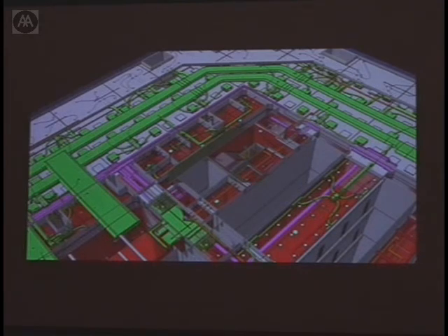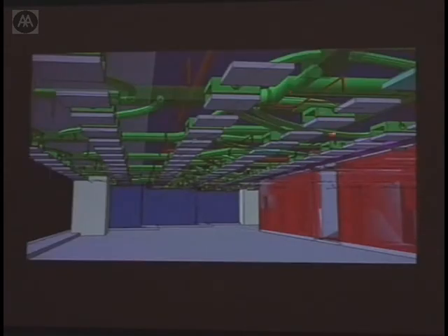And what we found is that the tools that we use allow us to capture pretty much every single miscoordination clash. What's interesting is that not only did we find there were a lot of clashes, but over half the clashes were within that one consultant, i.e. the mechanical guy clashing with himself, right? So his HVAC department would clash with his plumbing department. It's crazy, right? So they spent most of their time just sorting out their own mechanical systems before coordinating with structure and finishes and so on.